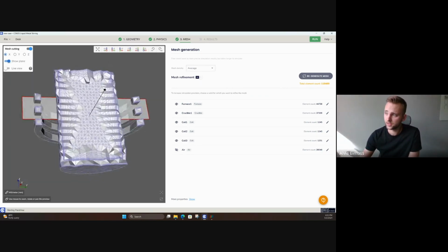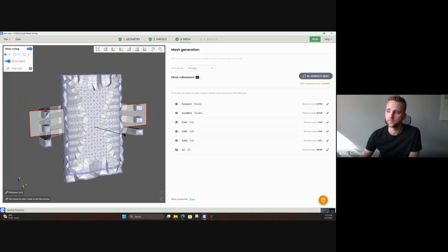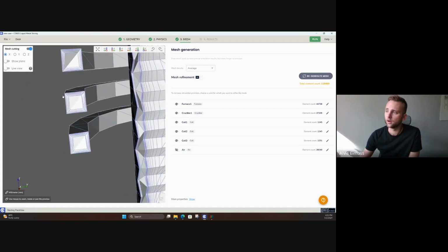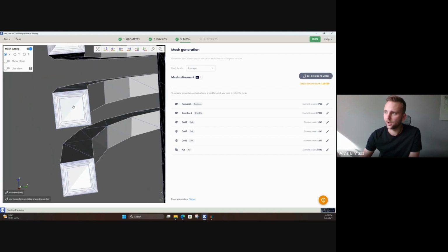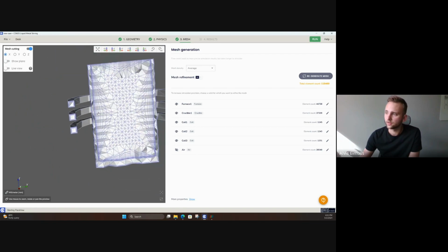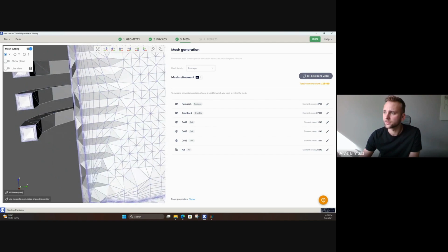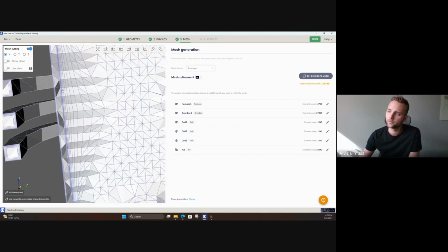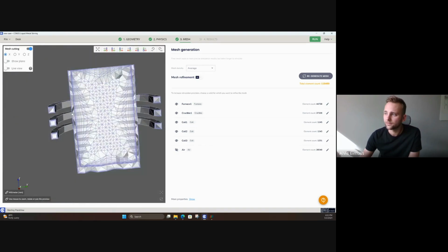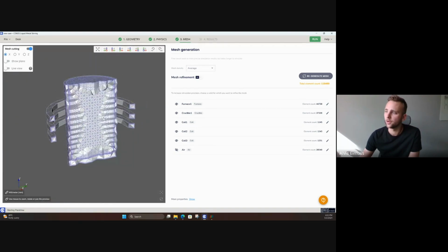And if we do this, then you can notice 2 things. So first of all, CENOS automatically generates what ANSYS calls inflation layers in the coils. And it also generates viscous layers in the melt, like this. So all of this is done automatically, but you still have full control over the mesh and also these layer